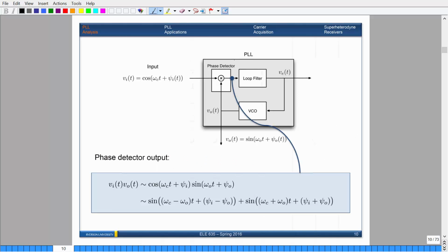Remember what I talked about, the phase detector. For now, we can consider this as just a multiplier. We'll talk about the general case later, but for all intents and purposes, just consider this to be a multiplication of two signals. So the output of the phase detector is basically taking this input, which is an unmodulated carrier. We're not putting a message signal in, this is just a carrier by itself. You're just putting in some sinusoid, so we have an unmodulated carrier of cos.